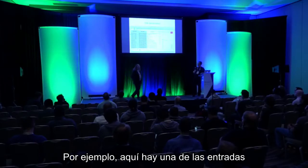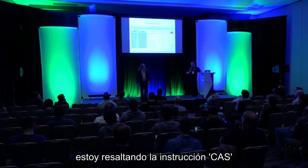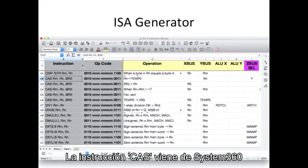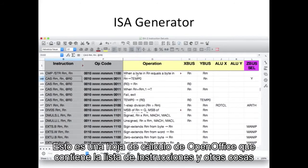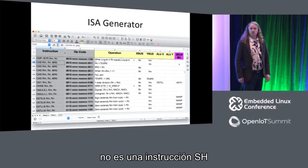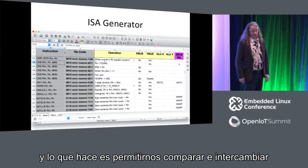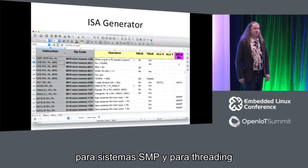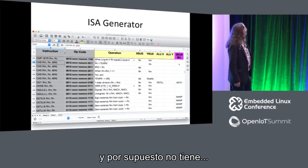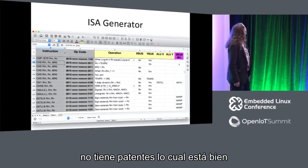So here, for instance, is one of the inputs, and I'm highlighting the CAS instruction. The CAS instruction is from System 360. This is an open office spreadsheet that contains the list of instructions and opcodes and so on. So CAS is a new instruction for jcore. It's not an SH instruction, and what it does is it lets us do compare and swap for SMP and for threading directly in the hardware. And of course, it's out of patent, which is a good thing.